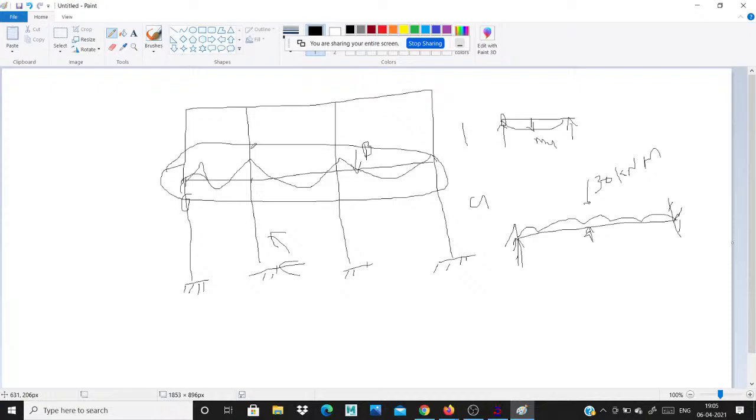Then you go for shear, same as what we discussed yesterday. This is our continuous support or any fixed support, and the shear is the same. You calculate the shear with the same procedure as yesterday, and calculate the moment in your fixed end support.